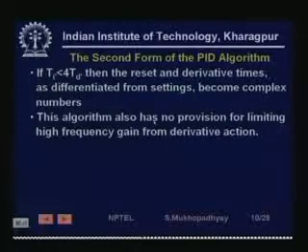On the other hand, the second form does not have that 1 plus denominator with the derivative term. That denominator is actually used for limiting the derivative gains, as we have pointed out earlier, because the sensor signal may contain noise, and then the derivative will give you very noisy signals. If you try to differentiate noisy signals, we get very noisy signals. So, there is a need to restrict the high frequency gain of the derivative, so that noise is not amplified while the process signal gets differentiated.